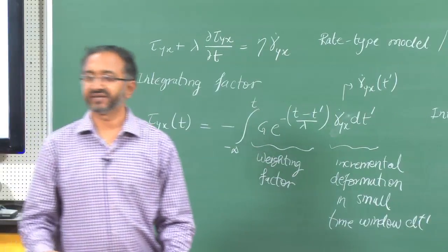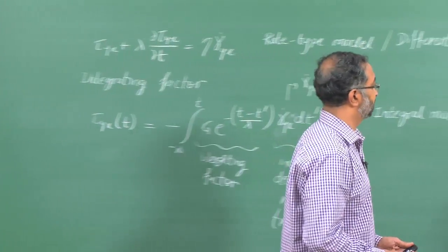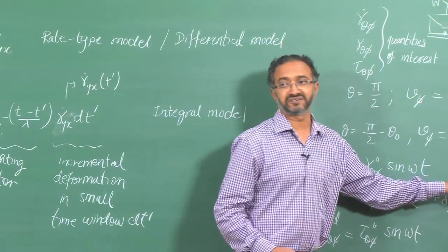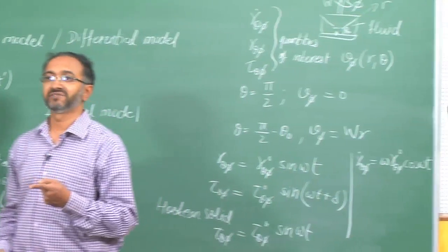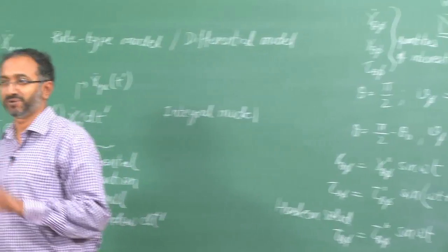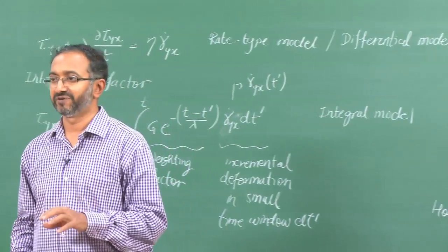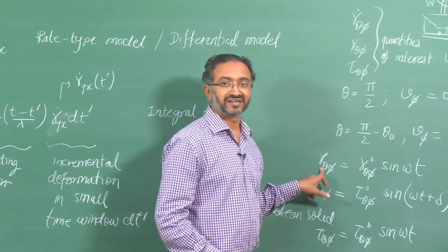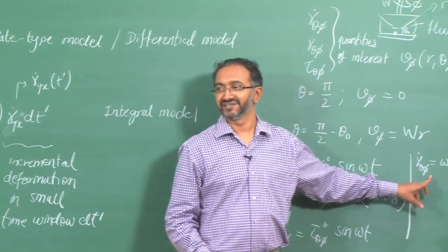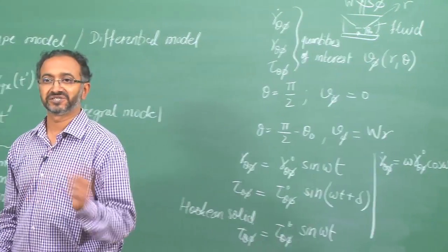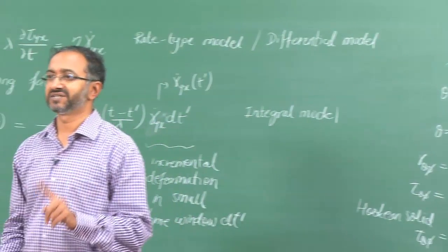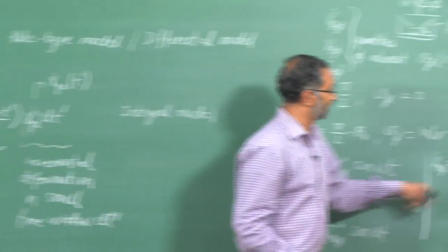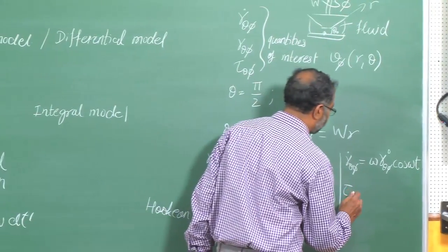So, this is just a derivative, and we should again remind ourselves that the transformation from strain to strain rate is done by a simple time derivative, because we are looking at linear response, because we are looking at small deformations. In general, the partial derivative of strain is not the strain rate; only because we are working with small deformation can we make this transformation easily from strain to strain rate. And so, this is the strain rate, and therefore we would expect for a Newtonian fluid